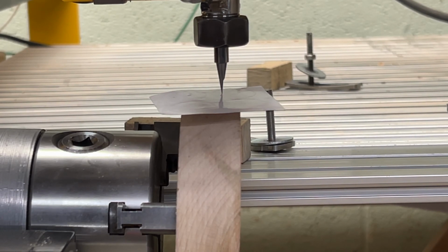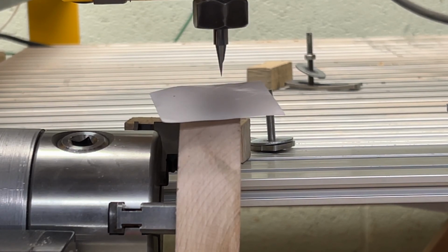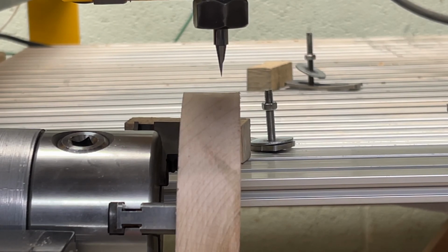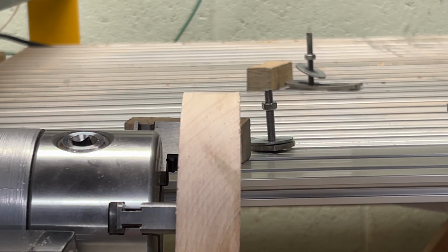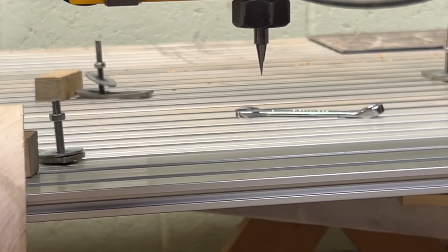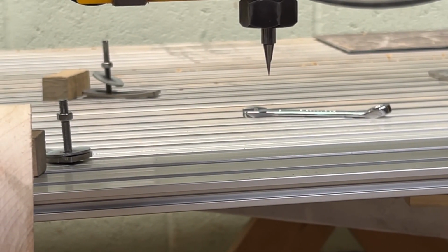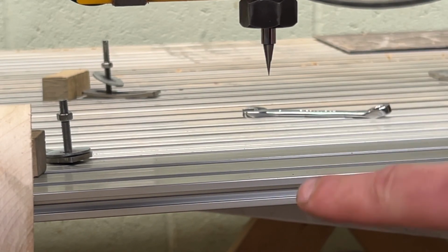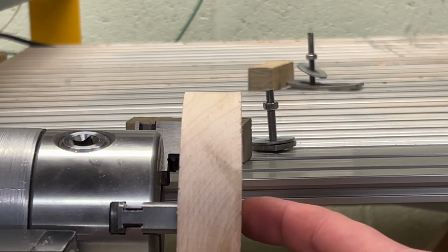Now we're going to pick it up in the Z-axis and move it over out of the way. Alright, now the cutter's out of the way. We're going to bring it down 2 1/4 inches. So that'll put our 0 right dead center of the coaster.